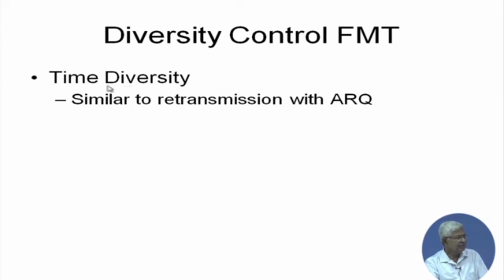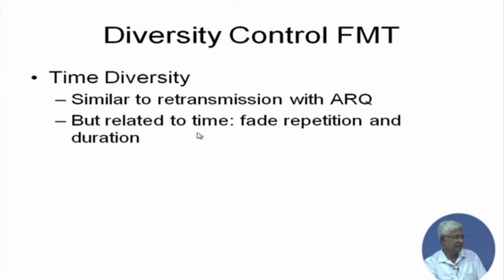This cannot be used for real time operation. Say you have an audio conversation going on, or video communication or video broadcasting going on. At that time you cannot suddenly stop the transmission and wait until the impairment goes away. A rain event is taking place for a few minutes, and after that you start the discussion on the video conferencing. That's not tolerable. So this is used for non real time communication.